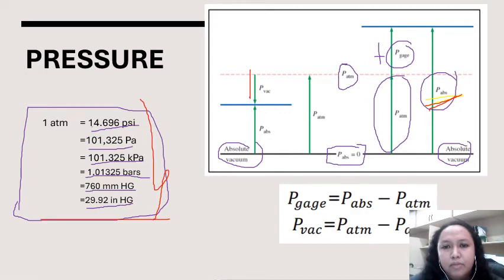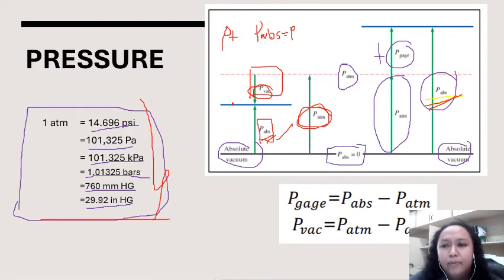But when it comes to the problem, given sa'yo sabi doon, vacuum pressure, hanapin daw yung absolute pressure at a certain point or the certain elevation, or a certain space. So, atmospheric pressure minus that. Okay. So, makukuha mo na yung absolute pressure natin. Okay? Paikot-ikutin mo pa rin yan. Pag positive class yung gauge, so, yung absolute pressure natin is atmospheric pressure plus the gauge pressure. Ayan, class.